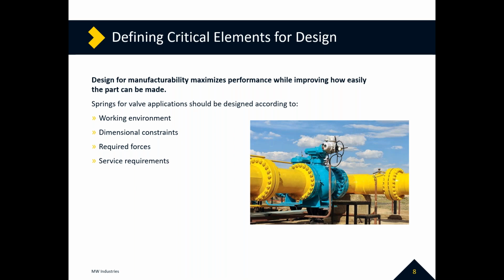We want to know the required forces, and the required forces are very important, probably the most important, and again, I'm going to highlight a relief valve application. You want to make sure we are able to achieve that force at the lowest stress possible, so that the valve operates well throughout its life, because it's a very critical application, right? Valve springs, safety relief valves are very critical.